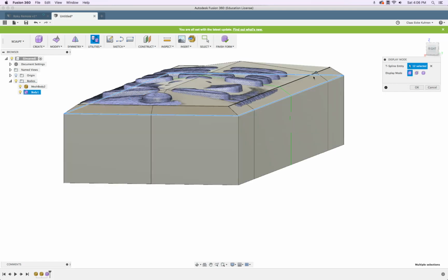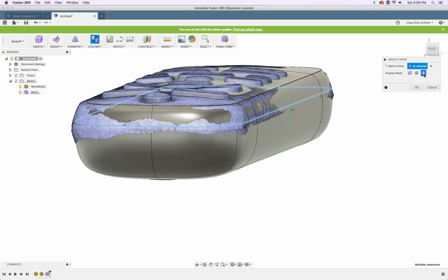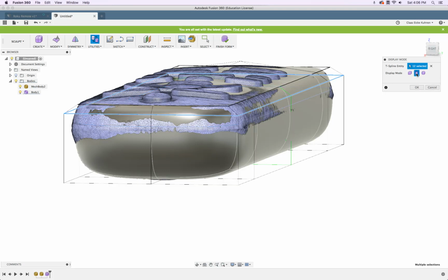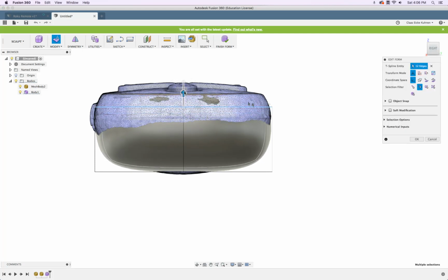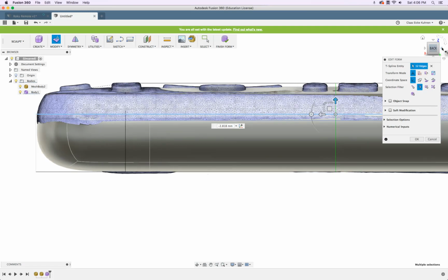And I deal with very basic faces, and the software creates super smooth surfaces for me. And if I click on this icon here in between, then I can see the result and the basic modeling geometry, which tells me these lines are a tick too high. So for the moment, I bring them down to where I would like them. We might have to adjust this afterwards anyway, like there. Very good.